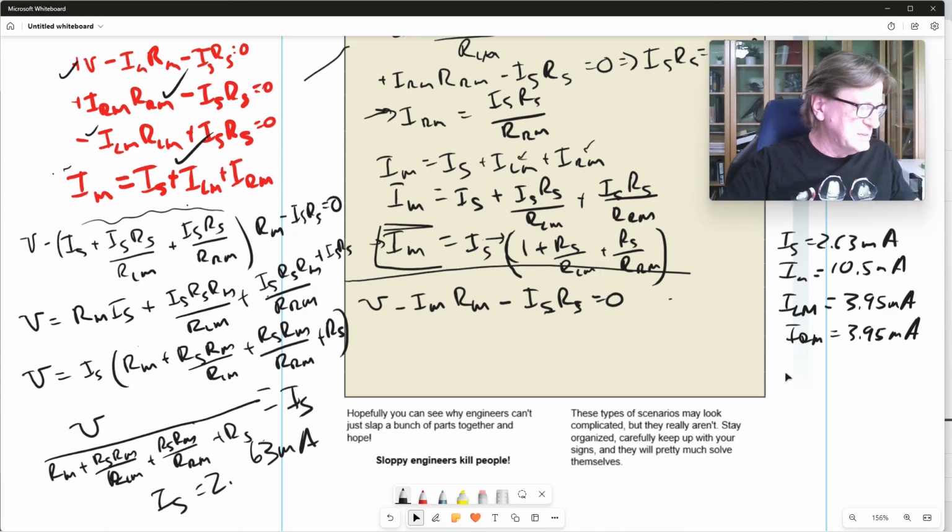So now we go back to our original circuit, and we see, do any of these cross the limits? Well, the microcontroller is going to be a problem, right? The maximum current our microcontroller could handle is 7 amps, and we're going to be running 10.5 amps through it. So we just fried our board. The sensor is okay because it needs to be less than 4. The motors are okay because they need to be less than 5 milliamps.